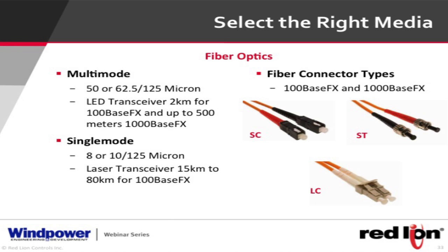The one image that's actually showing here is an SC type connector. And think about it, it snaps in, SC. And ST kind of looks like a BNC type connector where you push it in, it's got a little spring loaded, and it hugs in. A benefit to that is if there's any vibration at all, it's spring loaded and it's actually twisted on there. So if there's vibration, that'll help you.